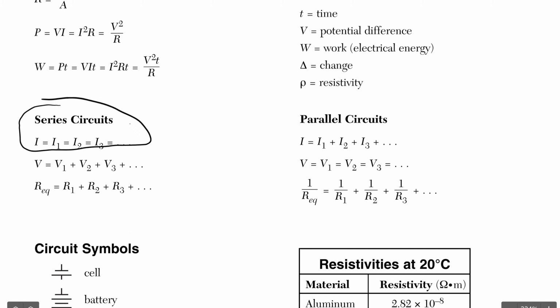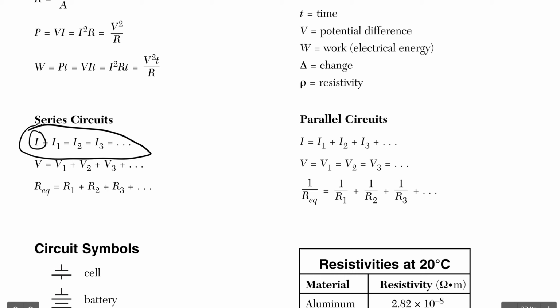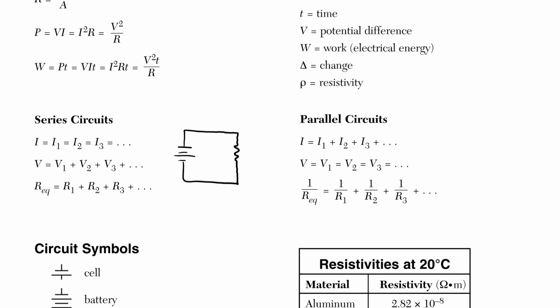And they're saying, why would you want the ammeter, which measures current, to be connected in series with your circuit? Because you want the current going through your ammeter to be equal to the current in the circuit that you're measuring. So for example, let me make a little circuit here. If I wanted to measure the current in the circuit, I would put the ammeter right here.